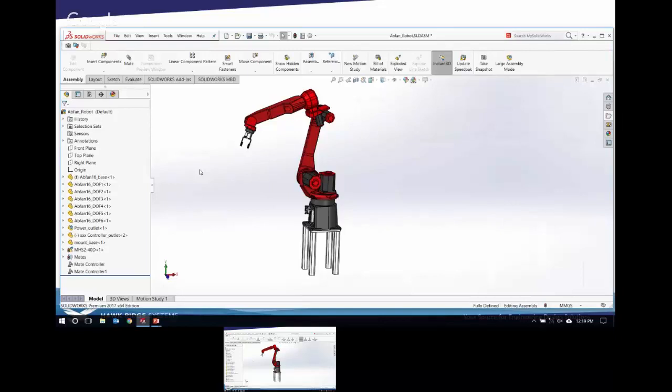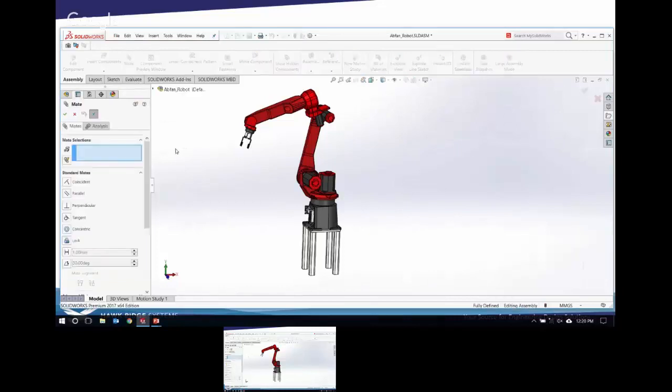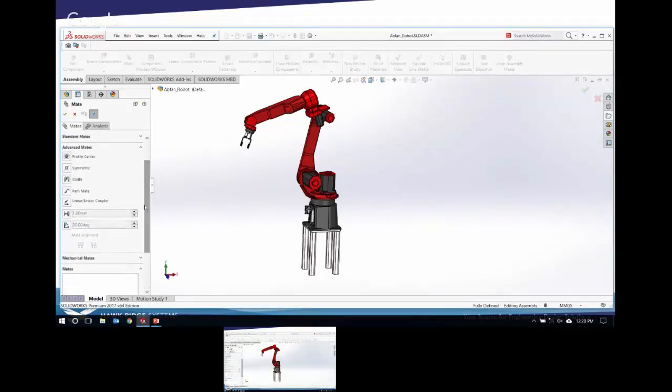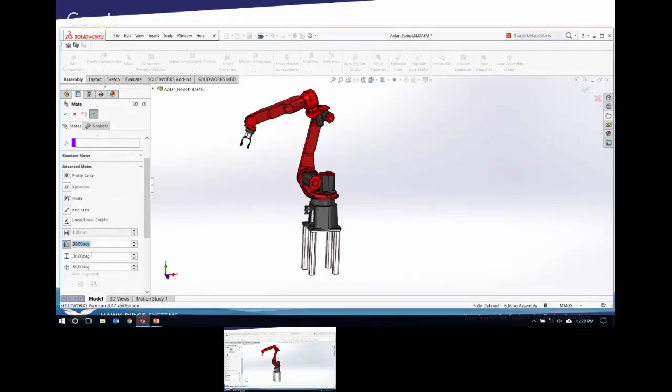Yeah, so you can do a limit to the movement if you do a limit angle mate or a limit distance mate. That would be defining it before you got into the mate controller, but when you're actually defining your mate, so that would be under advanced mates. And then you would define here some angular distance between objects, and you specify your maximum and minimum.